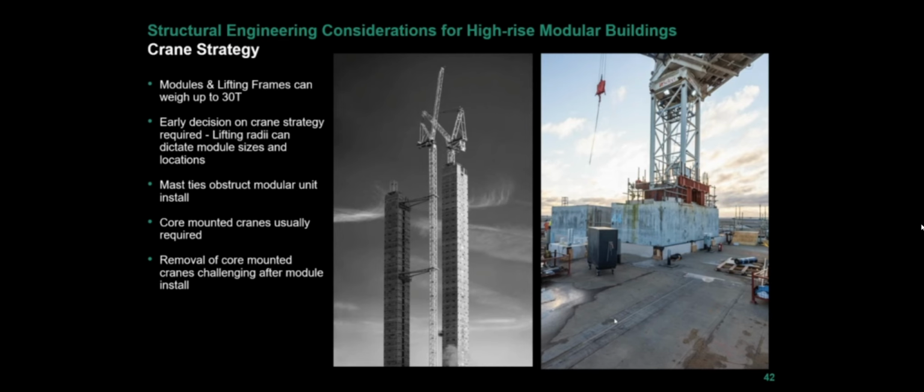But then the challenge is removing the crane from on top of the core after the building, because we generally can't rebuild the middle crane because it's probably blocked by modules. We've looked at tying to the modules, but that is very difficult as well with the tie forces. They're very big for the module connections.